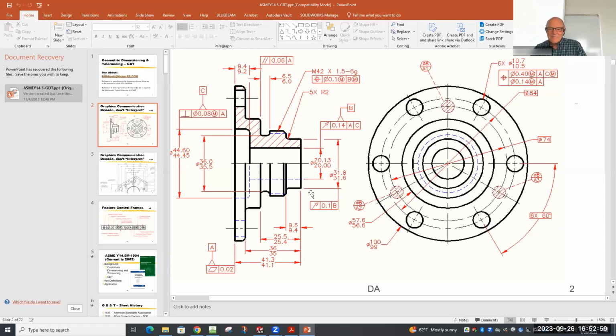The problem with all this stuff, there's actually a phrase for it called decorating drawings. Engineers get almost no training in this when they're in school. In fact, I've had students come down, mechanical design students from Orono, and they'll take a mechanical design class down here because they don't understand this stuff. The problem is they think they should. And so here's what they do. They decorate the drawing with this stuff and put really small numbers in there, i.e. expensive numbers. So it's a terrible way to design, but it happens enough that in the industry, in the trade, there's a phrase for it, decorating drawings.